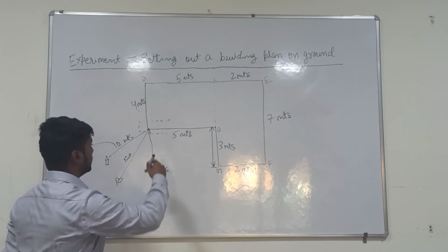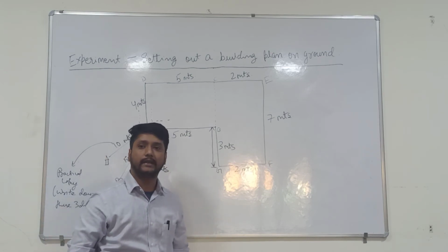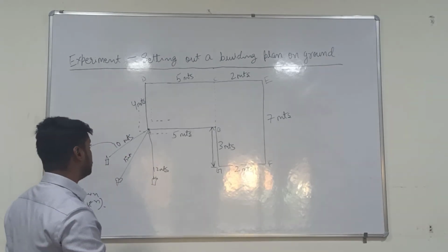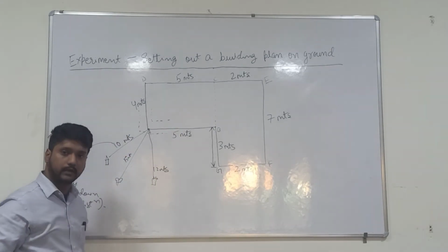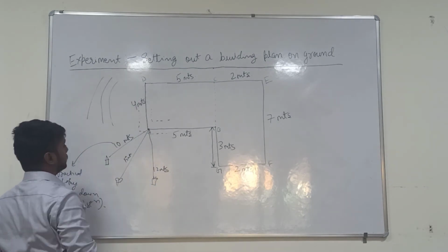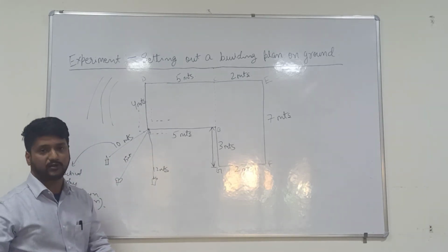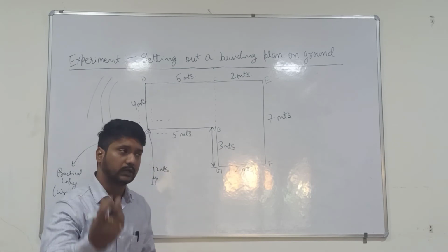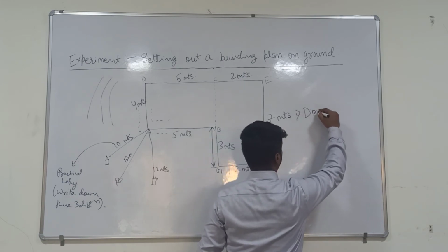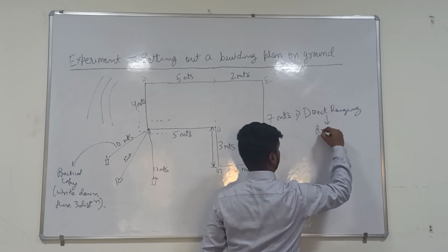Now from point A, we have to move forward towards the B direction, but when you go to the site, is it always certain that you are drawing a straight line? It's not, because human errors are possible, and you might think that you are moving in a straight direction, but it might take some curve, or some angle, or some irregular shape if you don't follow the concepts of surveying here. So first of all, we have to understand 2 concepts here. The first concept is called direct ranging, which is used to draw straight lines on ground.